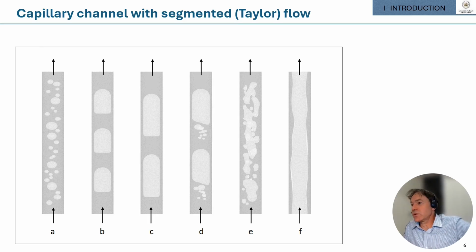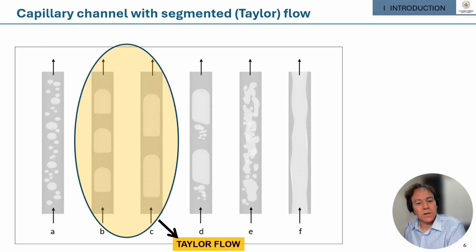Applications were developed especially for the manufacturing of fine chemicals or pharmaceuticals, but also compact heat exchangers. Now, what is really happening is that in these channels, only a few millimeters in diameter, both gas and liquid are flowing in the same direction. And if you change that ratio or the conditions, the speed or the liquid itself, you can obtain at a certain point the so-called bubble train or Taylor flow, where alternating gas bubbles and liquid slugs flow through these channels.